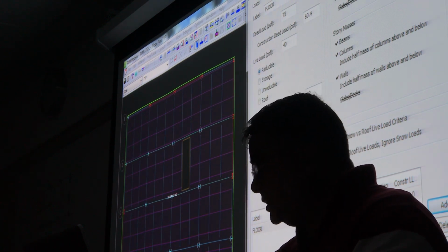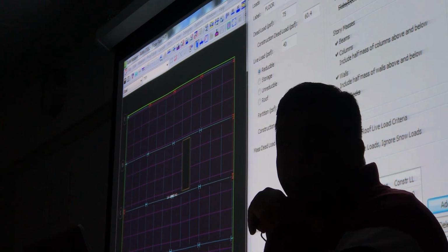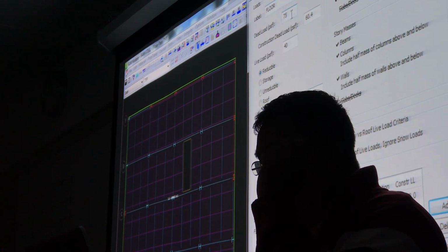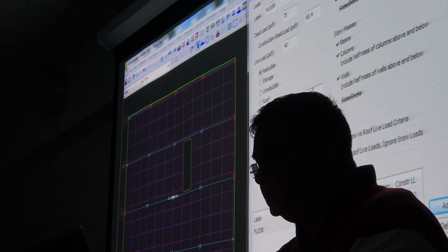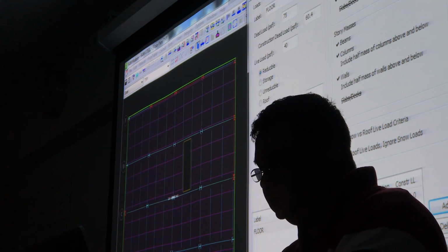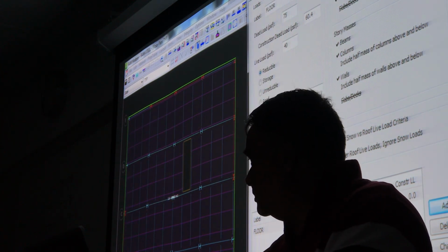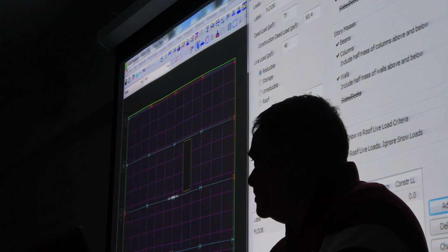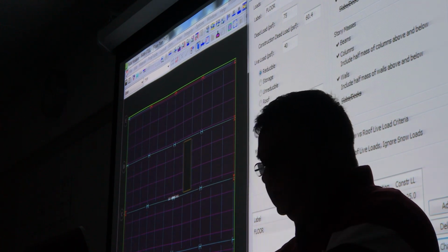Mass dead load. Mass dead load is for seismic force, because the seismic force acts at the center of mass with the mass, right? So I need mass dead load to be 75 PSF at least. Sometimes we add half of the partition load, another 5 PSF, maybe 80 PSF. If you think that your mass could be a little bit more, feel free to add that. Now don't add like another 200 PSF. Maybe another 10, 15 would be fine. Not more than that. And then I need to change it.